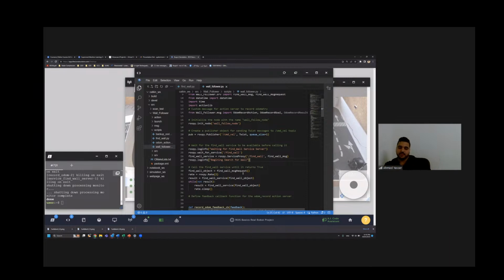Perfect, very good. Multiple nodes can call it. It's important for me to see if you have understood this, because then you are going to use this concept also in your programming of other robots. When to decide to put some code inside a service, and it's what you mentioned: because you want to call it several times and from multiple nodes, not just from the wall follower, but maybe another program inside the robot needs to align the robot for some other reason. For example, when the robot reaches the end, it has to present a message to the people in front of the wall, so it has to align again to the wall. So the node that will show the message to the audience will also need to call the find wall service.